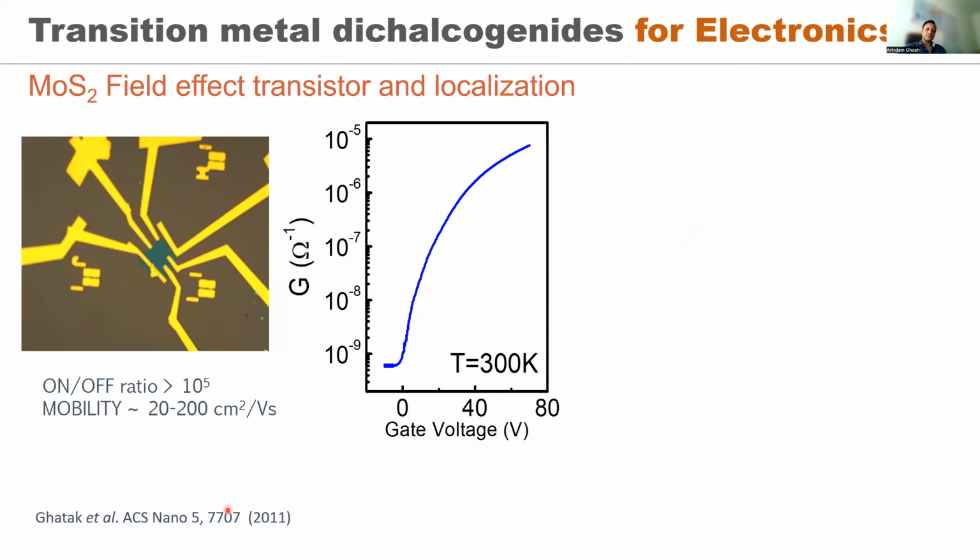Right, so as far as two-dimensional materials are concerned, it will not be too wrong to say that the majority of the work is in the range of graphene and transition metal dichalcogenides because they are semiconductors. Of course, there are now magnetic 2D systems and others, but by and large. So if I look at molybdenum disulfide, you can see this is how a typical electronic device on a molecular molybdenum disulfide looks like. You have a single layer here, you put electrical contacts, then you measure the current between the electrical contacts as a function of gate voltage, which is acting as nothing but a field effect transistor.